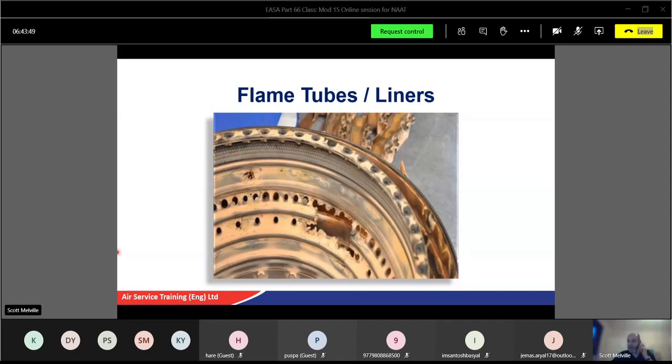Carbon deposits are intense black, and sometimes they can be mistaken for holes, but it's purely carbon. If you suspect that, change the angle of your borescope equipment or get a second opinion just to make sure. Because as you're looking in there, your eyes can get a bit funny, and sometimes even getting a big screen helps. With newer types of equipment, you can plug it into the big screen and magnify it, and that might help you out as well. Lots of different ways.